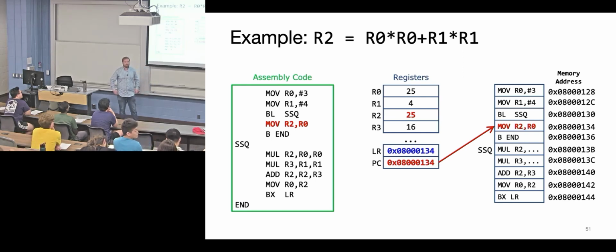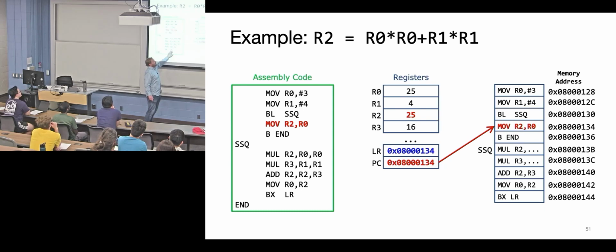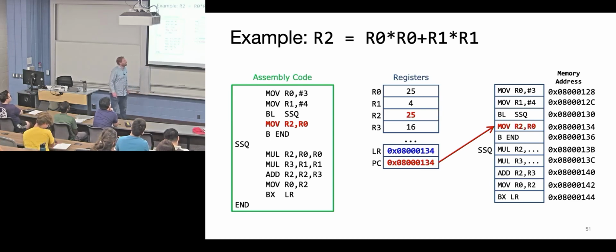Branch normally uses labels too, right? Correct. But is LR a label? Is it a register? Is it labeled for a register, I guess? Like other branch instructions use it? You're branching. BX is branch to register. So you're branching to the register defined by this. You could branch to R3, anything else, I suppose, but you're going to do the link register specifically. So it'd be a branch to a label versus a branch to a register.